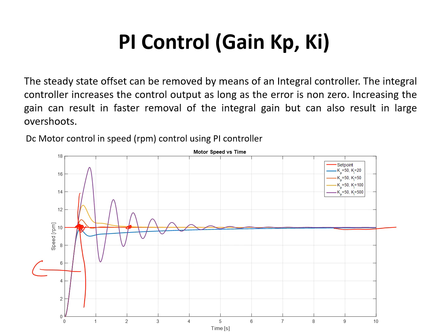This is the first time we're not actually increasing or decreasing the error term. So we overshoot, right? And this is now where the error term is negative. And now the integral term is reduced, right? Until eventually, if the gain is very high, we will have the error term decreasing too much until it becomes 0, and we have this slightly oscillatory nature until eventually it settles down.